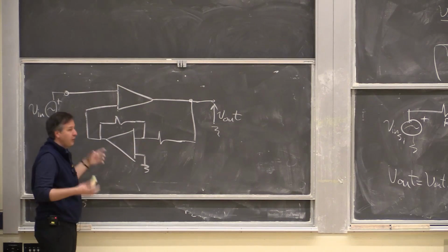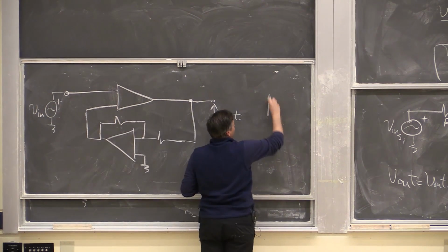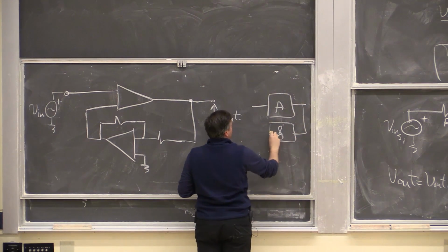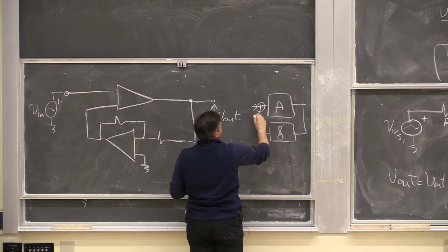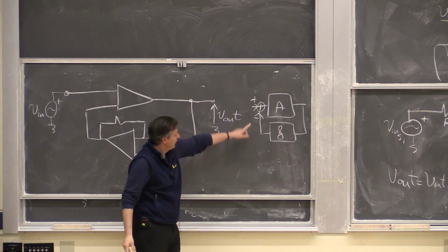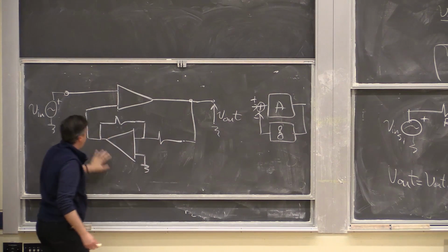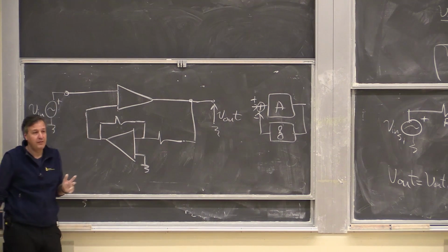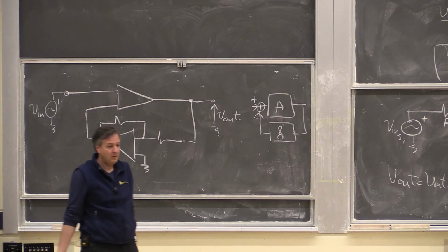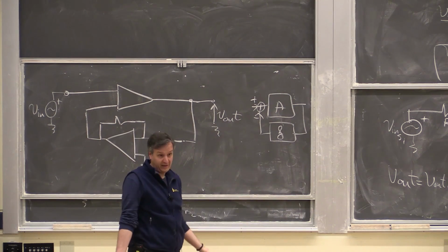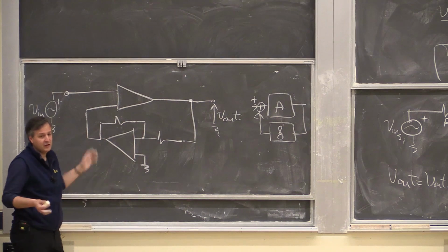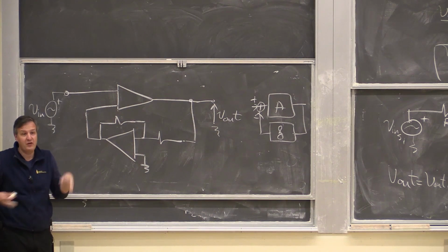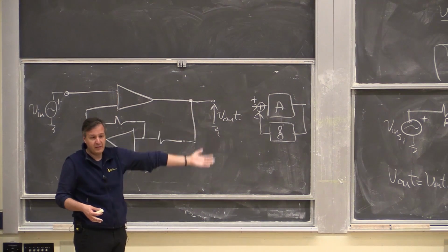Yeah, so this is the feedback block. If you think about how we did our feedback, it was the A block, right? And then was the F block that fed back. There was some essentially plus minus here, right? So this whole thing over here is the F block, the feedback block. Do you recognize that circuit? It's an inverting amplifier, right? We just did this lecture, right? So when you approach these circuits, that's exactly how you should think. Think about building blocks. What building blocks does it consist of? Can you recognize them? Can you apply already some things that you know about it?